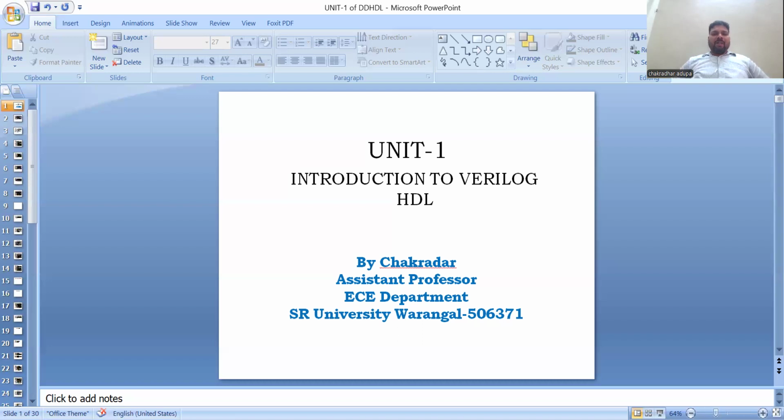In Verilog HDL, what is simulation, what is synthesis? Once a design block is completed, it must be tested. The functionality of the design block can be tested by applying stimulus and checking results. We call such a block the stimulus block, where we provide all possible combinations of inputs such that we are able to test the output for each and every corresponding input combination. So this set of input combinations is called stimulus.